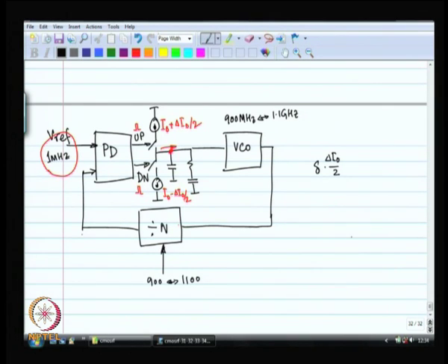That is the extra charge that is going in, charge divided by the capacitance, is the amount of voltage increase. All right. So, this is the problem, and what I am suggesting is increase C plus Cx, increase the capacitance.